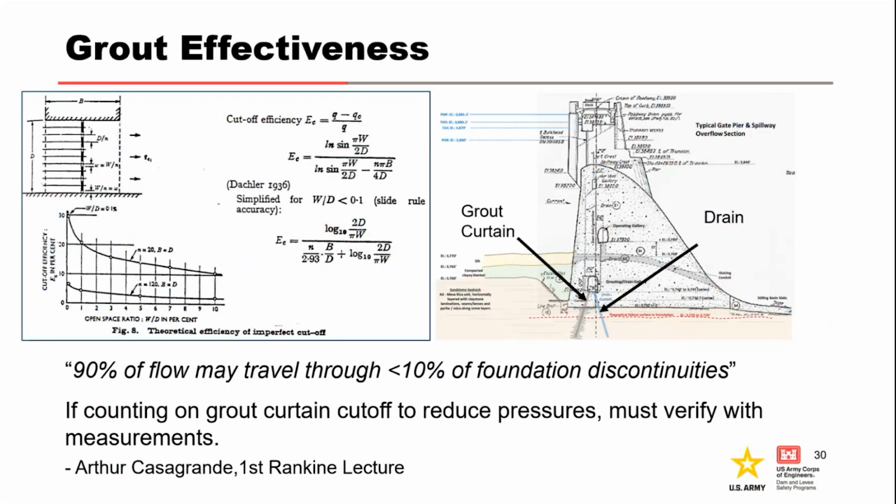So I'm going to touch quickly on grout curtains. Dams usually have foundation drains, but then they have an upstream grout curtain. We cannot solely rely on grout curtains because we generally cannot get complete closure in our grout curtains, and just a small percent of opening can result in a significant amount of pressure that is able to get through.